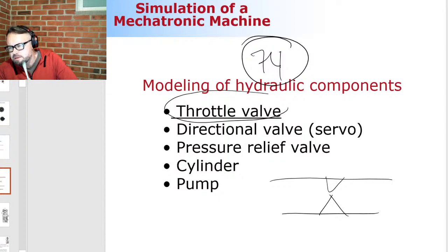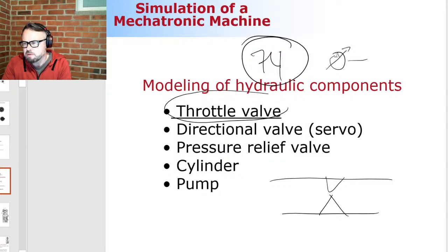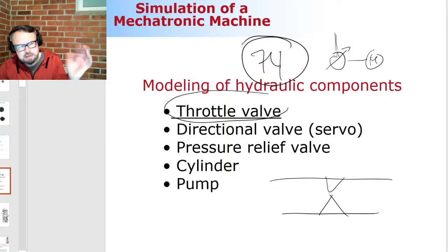hydraulics is typically controlled in a way that we have a pump that is producing energy. Maybe it's going to be a pump with variable displacement, and the pump is producing the energy for the system. And what happens in control components, which are direction valves and other components, is that you're introducing the pressure losses.